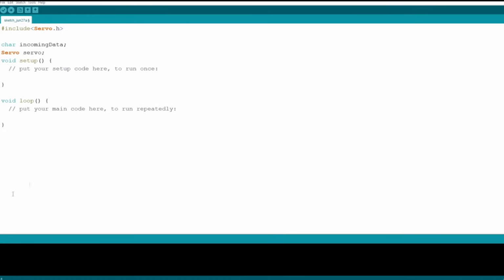So now let's define our servo pin. As you know, if you want to do this operation, we need to move inside our setup function. So let's delete this command first. And to do this operation, let's call our object. As you know, this is servo, and here we will use our attach method.